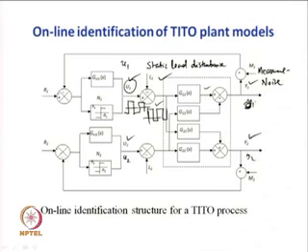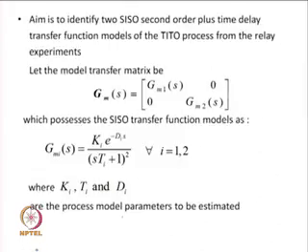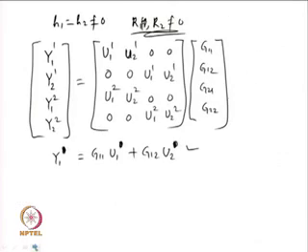So, the signal at this point, Y1, is given by G11 times U1. G11 U1 plus this signal is getting added here, so G12 and the input is U2 now. At that time, assume L1 and L2 to be 0 and the signal measurement errors M1 and M2 to be 0. Then you get the expression G12 U2. So, it is not difficult to get those simpler expressions first, which can ultimately be converted to matrix form and to the ultimate form given by this.